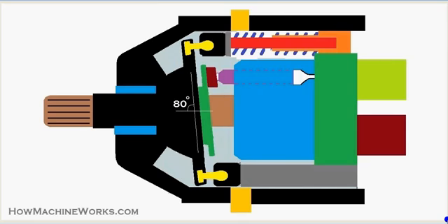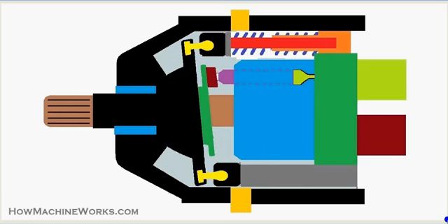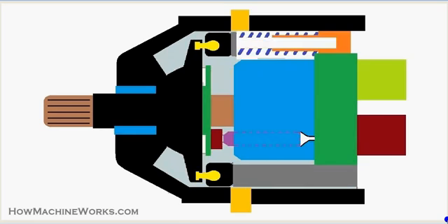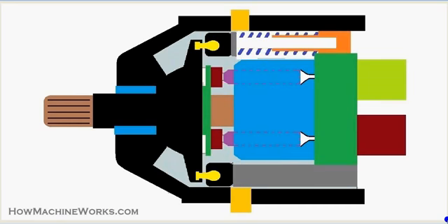As a result of that, a suction happens at the top. You can see at the top the suction happening over there, and the bottom piston you can see is actually moving towards the front because the swash plate is pushing it towards the front, so there will be the discharge. So as this particular cylinder block is rotating continuously, the pistons at the top end will create a suction and the pistons at the bottom end will create a discharge.